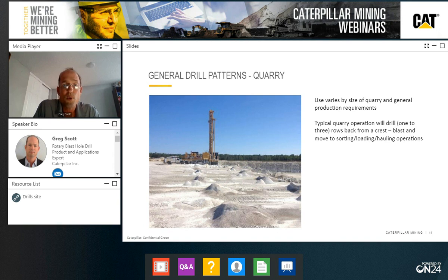We have more onboard drill power. So we have a little bit more CFM and higher working pressures on our compressor, for example. Or if you're in a tricone or a rotary application, we've got a little bit more feed force and we've got more rotary torque. If we're doing double pass or multi-pass operations on a fixed platform drill like this, the pipe handling system is more robust. It's a little bit stronger. It can take the cycles over the short, mid, and the long term of this machine.